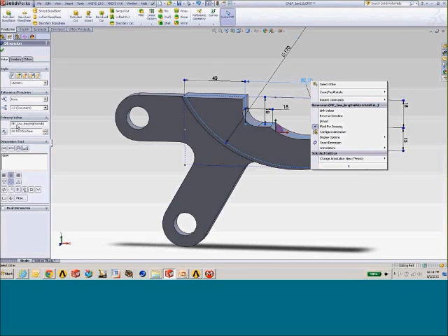And then in addition to that, I want to rename my parameters such that they have a recognizable name. Now, the reason I do this is when I bring geometry and parameters into the analysis environment, there's no way other than trial and error for me to figure out what the relationship is between a particular parameter and the geometry. Ansys doesn't know that.